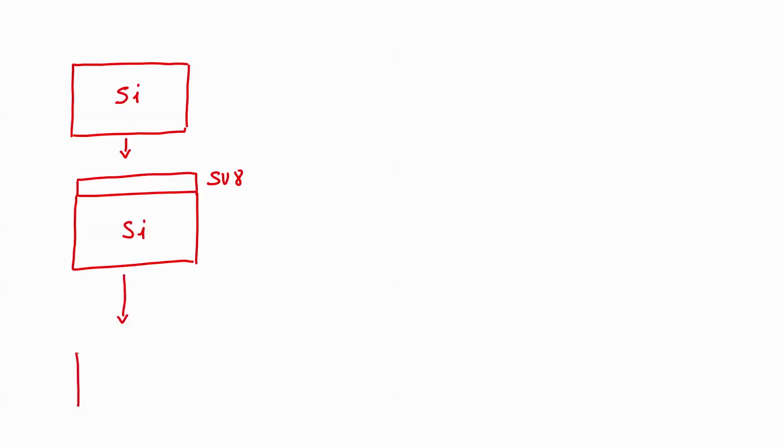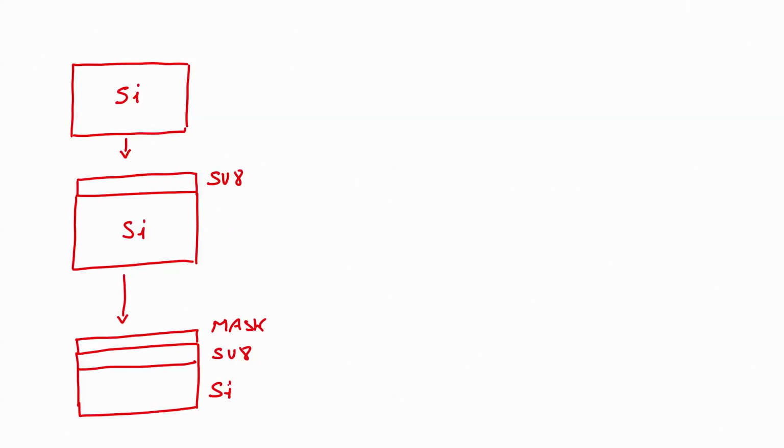Third point is you load the mask on SU8, right, and SU8 is which kind of photoresist? It is negative photoresist. Okay. So, after you coat SU8, you have to do soft bake and then load the mask, right, and you need to form a structure which will help to create your channels.